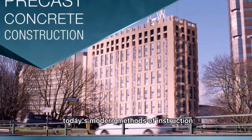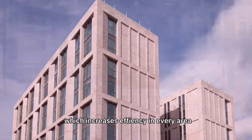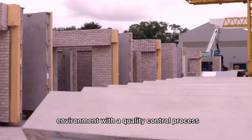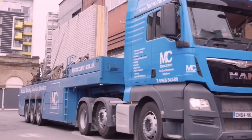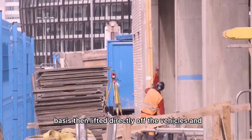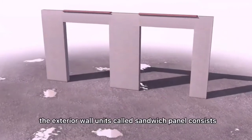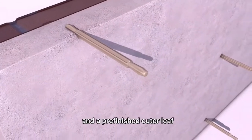Today, modern methods of construction have advanced greatly, particularly precast concrete, which increases efficiency in every area. The building components are constructed off-site in a factory environment with a quality control process that results in a robust, high-quality solution. These components are then delivered to site on a just-in-time basis, then lifted directly off the vehicles and installed into their final location. The exterior wall unit, called a sandwich panel, consists of a structural inner leaf, an insulating layer, and a pre-finished outer leaf.